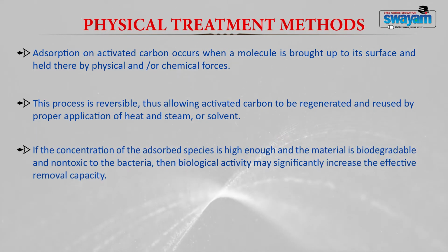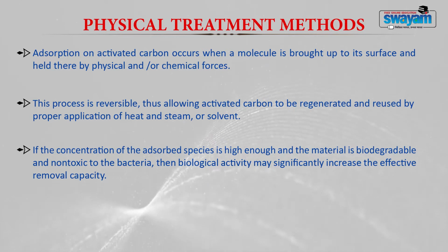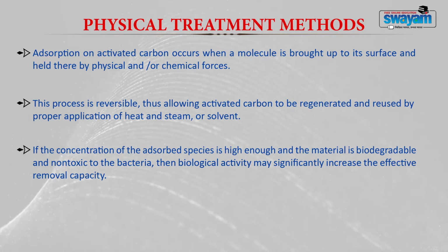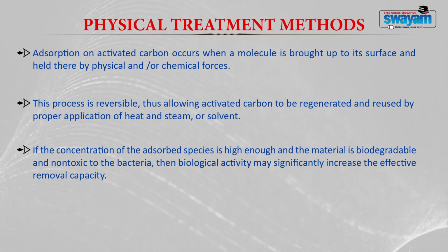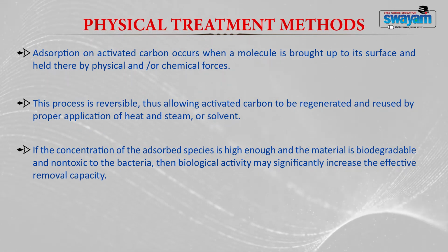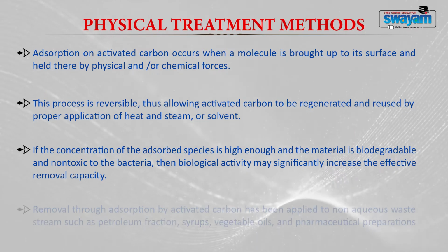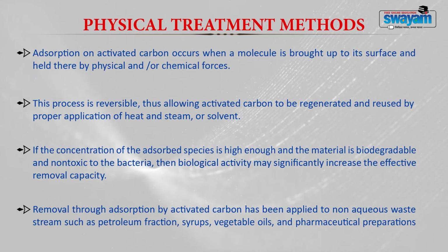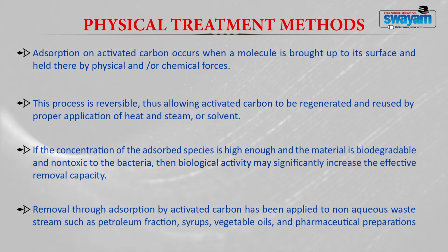If the concentration of the adsorbed species is high enough and the material is biodegradable and non-toxic to the bacteria, then the biological activity may significantly increase the effective removal capacity. Removal through adsorption on activated carbon has been applied to a number of non-aqueous waste streams like petroleum fractionation, syrups, vegetable oils and pharmaceutical preparations.